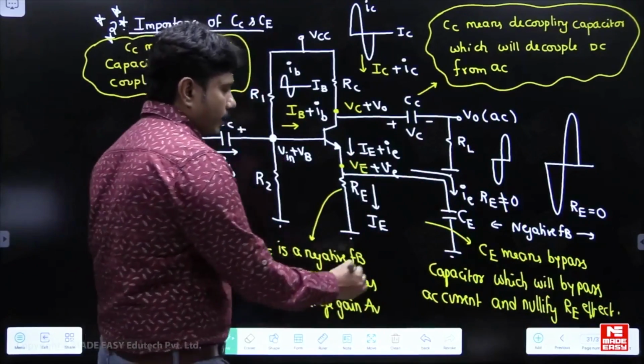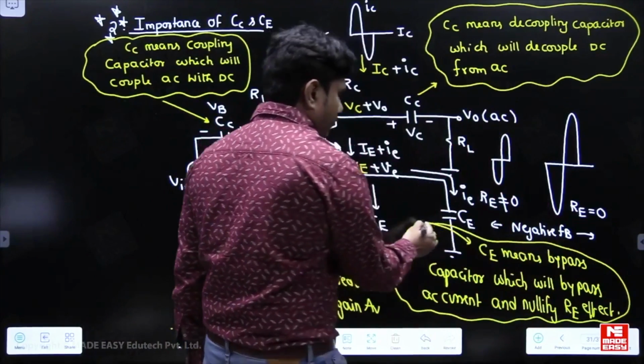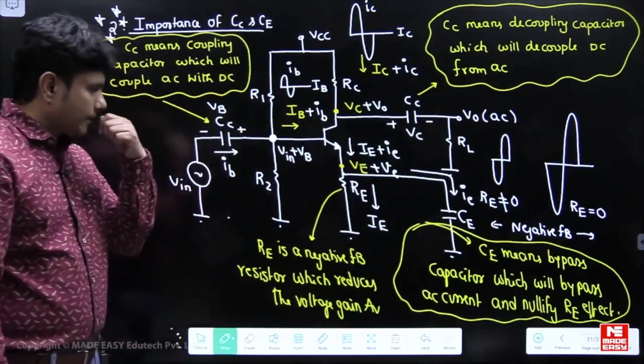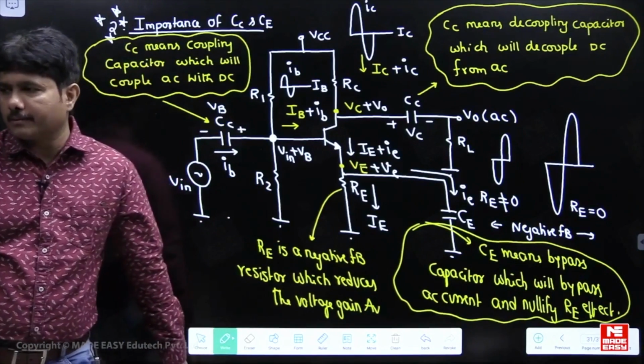So this is the story of the CE concept. It will just nullify the RE effect. So no feedback effect will come when you take the bypass capacitor.